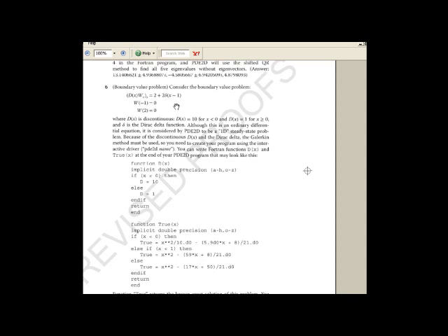So in the pendulum and spring problem, there were no space variables, and it was time-dependent. Here, there's no time, and there's one space variable. So it's a 1D steady-state problem, but you won't be able to use the GUI for this problem. You'll have to use the Galerkin method, which means you'll have to use the interactive driver, which asks a lot more questions, but you'll have to use it. You can't solve this with the GUI for a couple of reasons explained here.